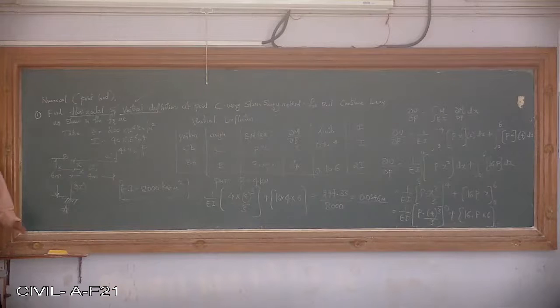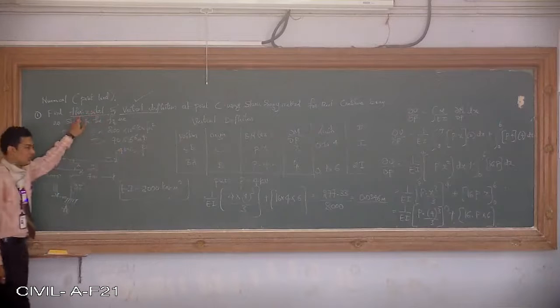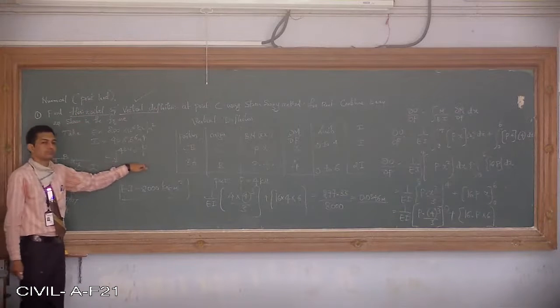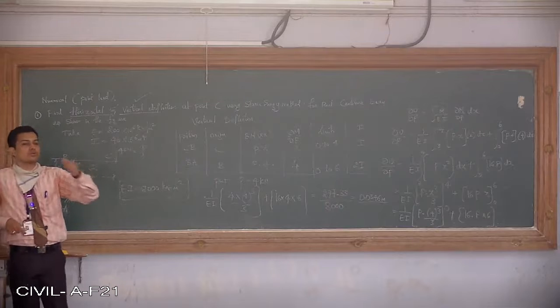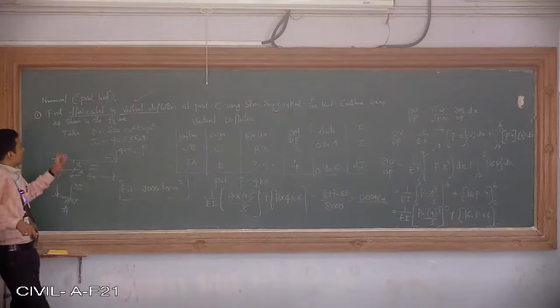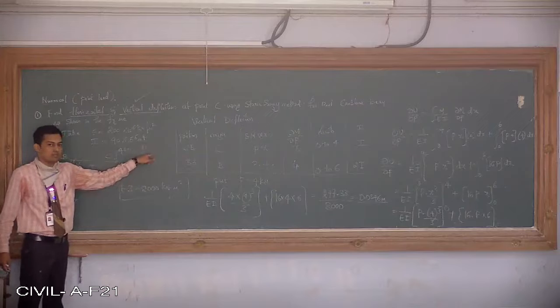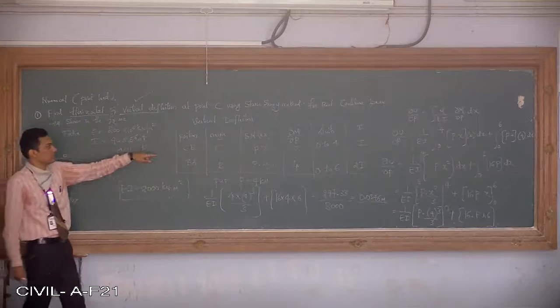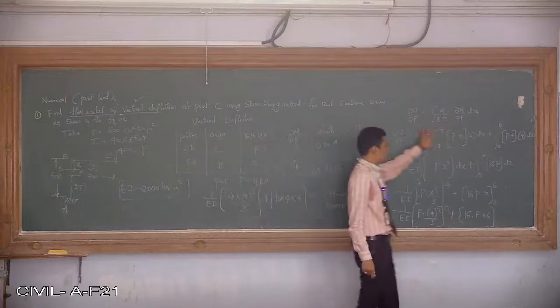Fine. So if you are going to find horizontal deflection, you have to take an imaginary load Q, solve it, take the derivative with respect to Q, then later replace Q equal to 0. If vertical deflection is asked for a vertical load, you replace it as variable P and take the derivative with respect to P. Then you put all these terms in the strain energy equation.